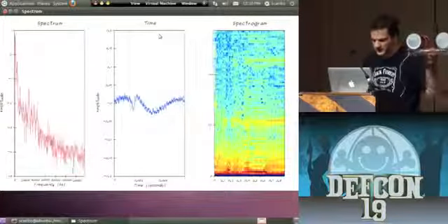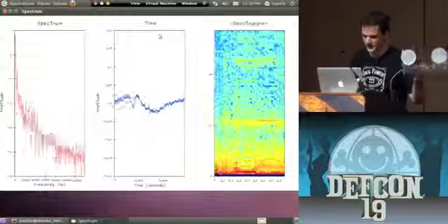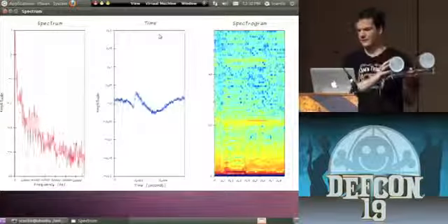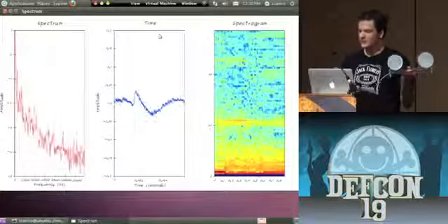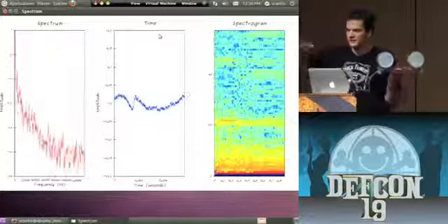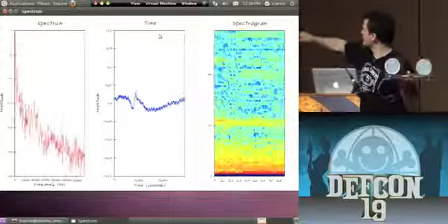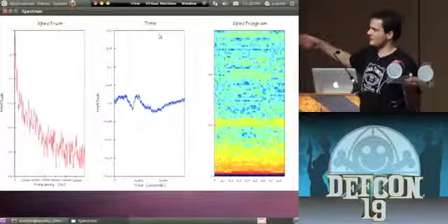And the other thing, which I haven't actually seen yet, which I'm a little surprised by, is that this thing operates in the Wi-Fi band. And there's a lot of noise. I'm not exactly sure why that's happening. That wasn't happening before. But what you do see occasionally is these pulses towards the top end of that. That's actually Wi-Fi signal bursts from the thing transmitting.